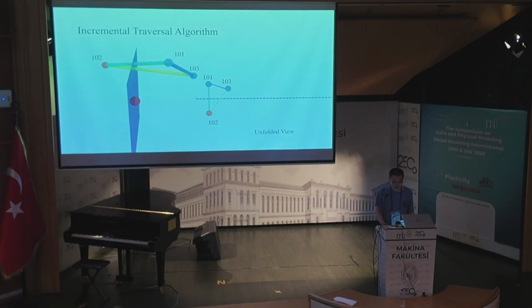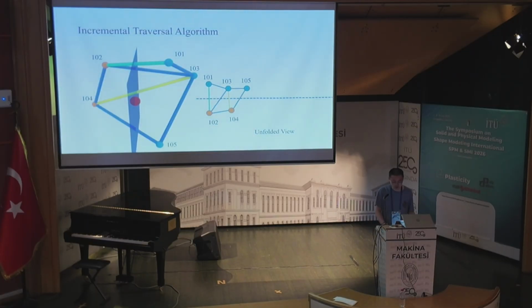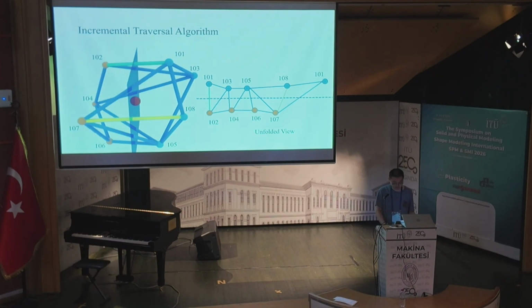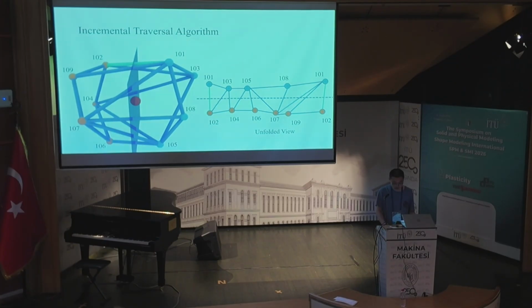The idea is to start from an initial Delaunay tetrahedron on the wall. We choose the Delaunay tetrahedron intersected by a target ring on the plane as the initial tetrahedron. And then walk to its adjacent tetrahedron along the local DeWall plane. On the traversal, when we return to where we started, the loop is closed, and the local DeWall for this vertex has been completed.